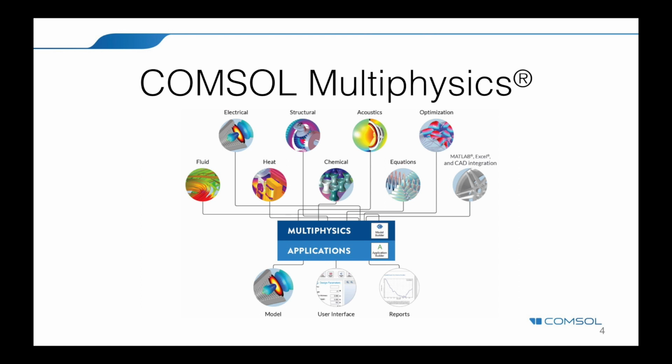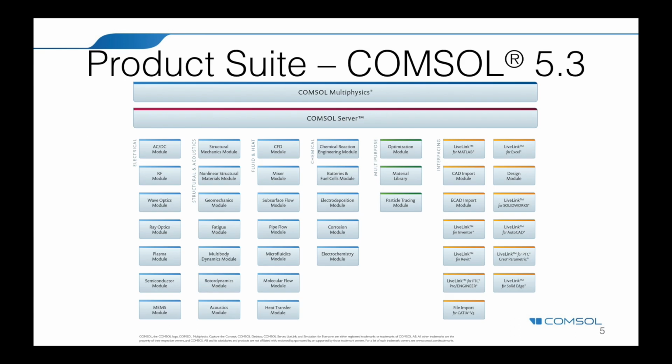The model we will look at today solves for the deformations and strains of a car door seal using nonlinear material models. Once you have completed your COMSOL simulation, the software allows you to create a customized app from the model, which enables you to deploy the analysis capabilities and results to collaborators, customers, or even colleagues around the world.